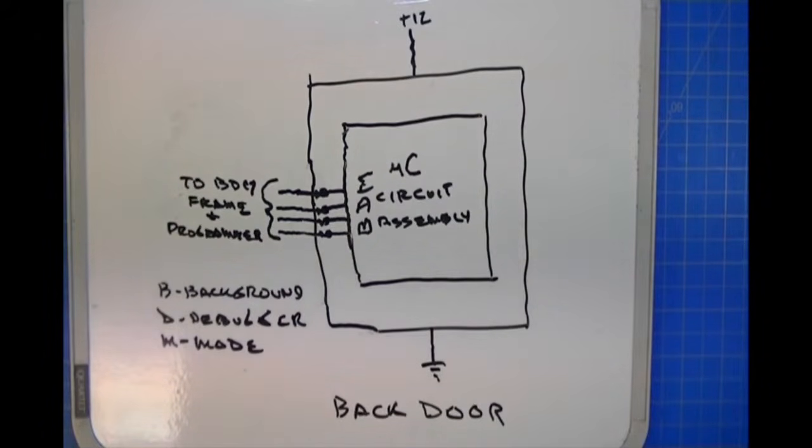Well, the problem with that approach was that in order to upload programs into the RAM of the microcontroller, it takes external pins to support transmit, receive, reset, and other conditions in order to communicate with the part. This is what our product does with the ACOM. ACOM is asynchronous communication. In order to communicate with some of these microcontrollers, we will upload our communication program into RAM and then run it, and that's how we're able to access and program the EEPROM. It's by a program that we send up to the microcontroller.